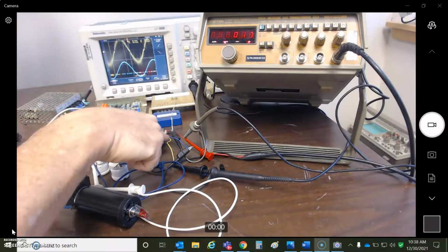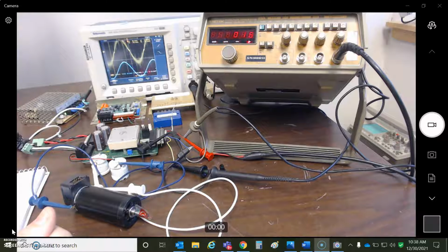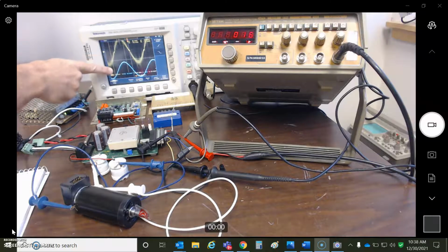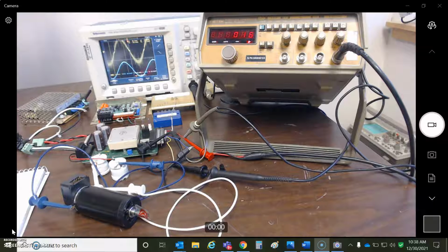And then coming out of the drive, we deliver current to the motor. Current is just torque and will normally cause acceleration, but you need a little bit of current to overcome static friction or dynamic friction. So there's a little bit of ability to control near 0. So the crossover distortion, you don't see it in the command, but you see it in the output. As you go through 0, you get a little bit of distortion on that. So we'll talk some more about that.